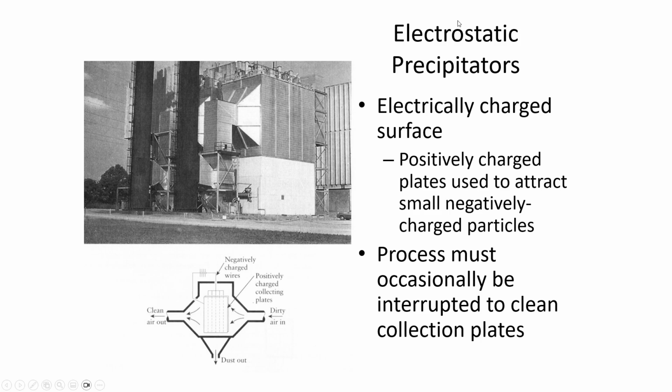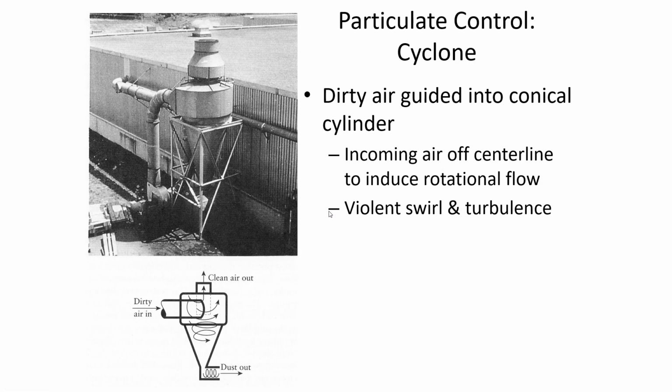So all of the processes we've been talking about so far are mainly focusing on removing particulate pollution. And the same is true for cyclones. Cyclones, what it is that the gas, the exhaust gas that has the particulates would come in and would be forced in a circular direction that causes centripetal forces that, because the dust is going in a circle, the particles would go to the edge of the cyclone, they'd settle down to the bottom of it and be removed.